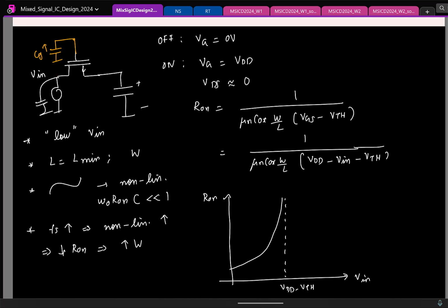That is a digital signal going from 0 to VDD. So this will be basically driven by a bunch of clock buffers, which is a series of CMOS inverters. I have a larger capacitance now, which means I should pump in larger charge to the capacitance. If the charge I should push here is higher, the current consumed by the inverters will be more.